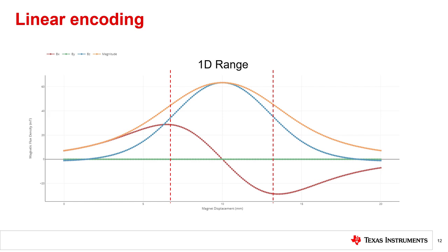Here, the maximum sensing range is limited to the region between the peak values, which is most linear around the center of the magnet. In fact, the size of this linear region often scales with the length of the magnet. Since increasing the size of the magnet may not always be a practical option, it is necessary to create a sensor array to expand the range using one-dimensional sensors.